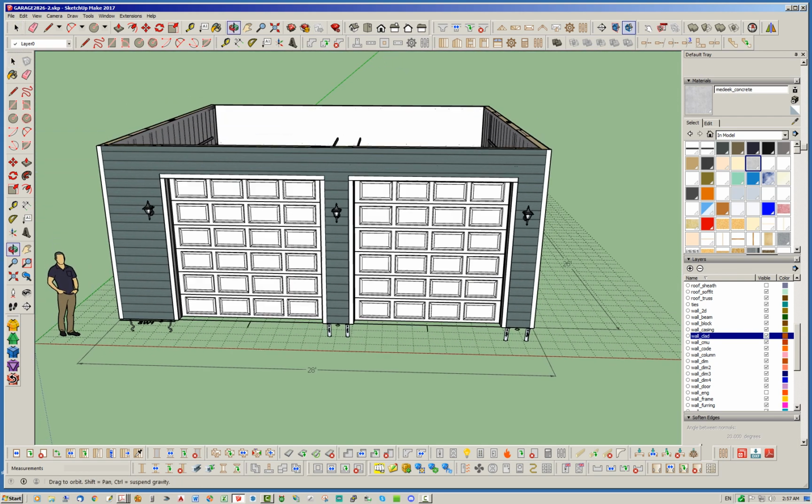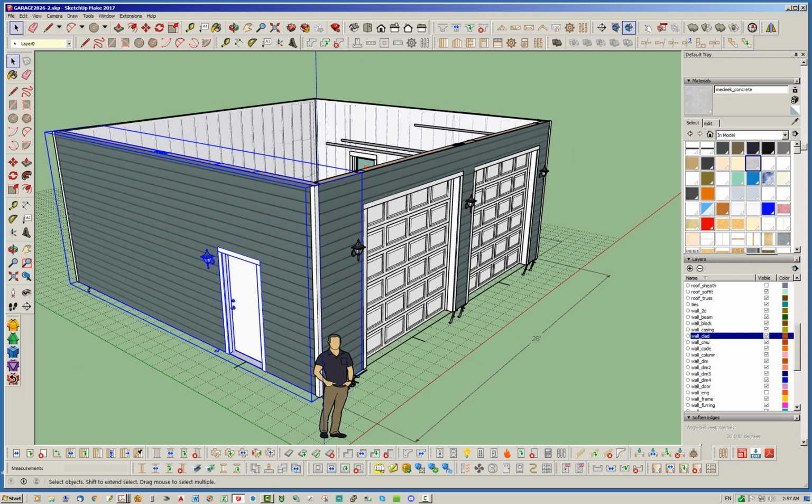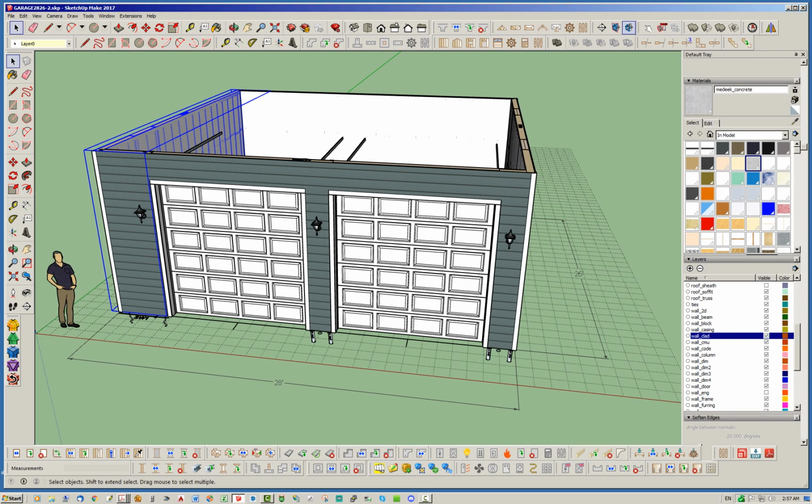And you'll find too with electrical components, they're actually kept within the wall panel. They're part of that wall panel assembly. So if you move that wall, all the electrical goes with it. And the plugin automatically recognizes that that's an electrical component, and it will keep it and won't destroy it when you regen the wall.